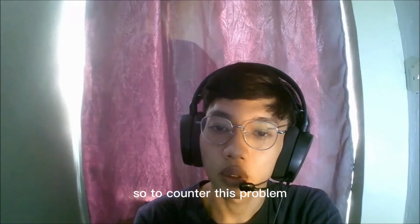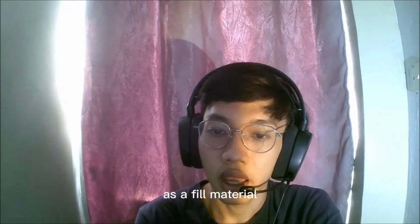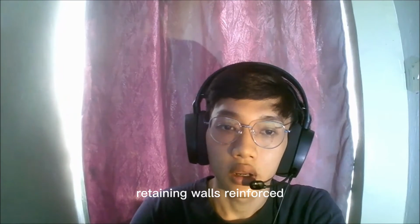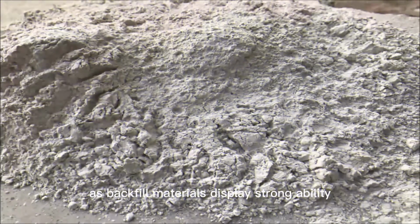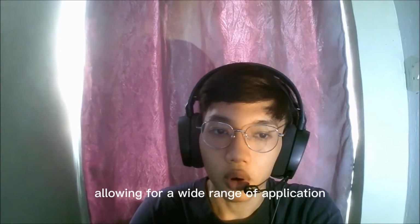So to counter this problem, fly ash can be used in geotechnical projects as a fill material for foundation, embankment, and retaining structures for its engineering properties. So how does it work? Retaining walls reinforced with geosynthetic materials and fly ash as the backfill material display strong ability and low settlement at a moderate cost, allowing for a wide range of application.